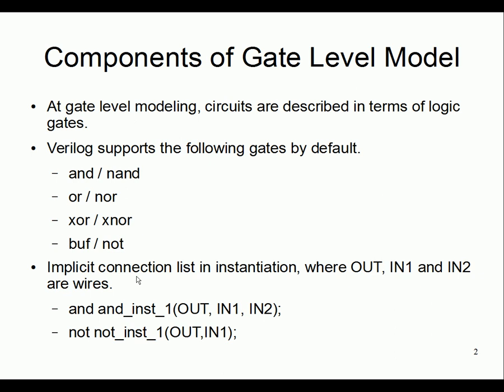That is the more explicit style of defining port connections, where it is clear which wire goes to which port. A module also has the ability to do an implicit connection type. This is not restricted to basic gates; for a behavioral module as well we can have an implicit list.